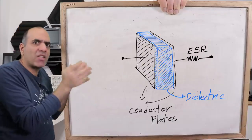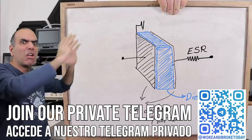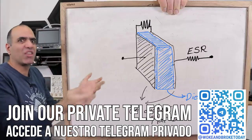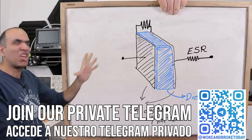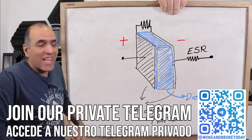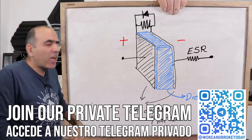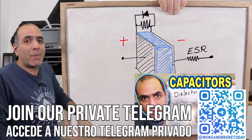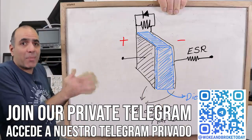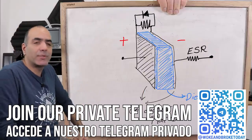Also, even the best dielectrics can leak very little current that we can show as a super large resistance. We always ignore it, it's so large, like giga-ohms. And then we have polarized capacitors like electrolytics, where the dielectric is such that it acts like sort of a diode. I explained all these in my video about capacitors, but any part of a capacitor can degrade, causing a less capaciting capacitor. It's not a word!